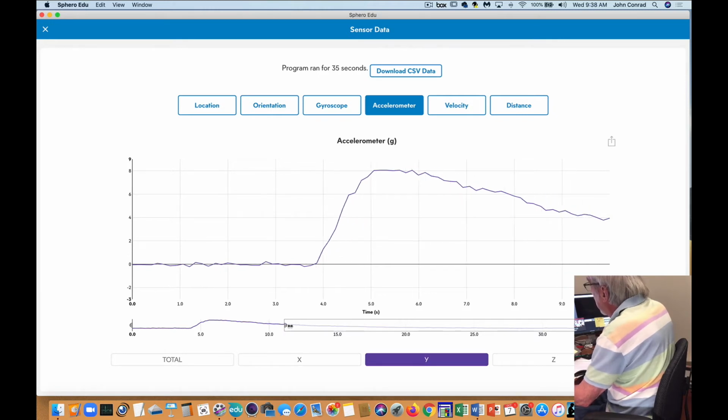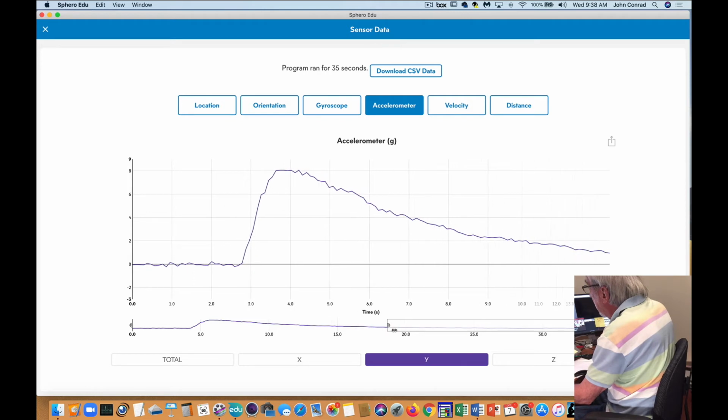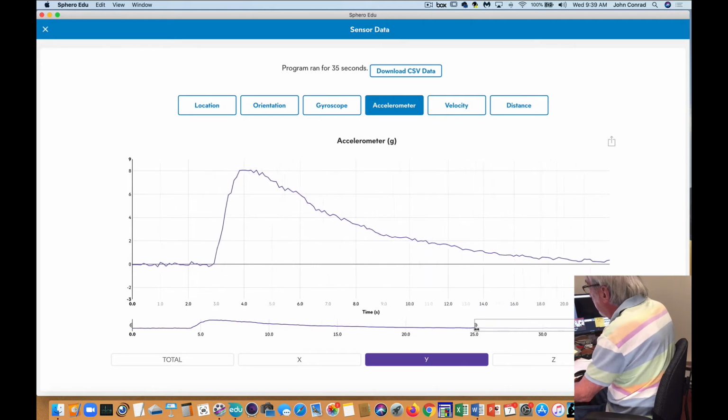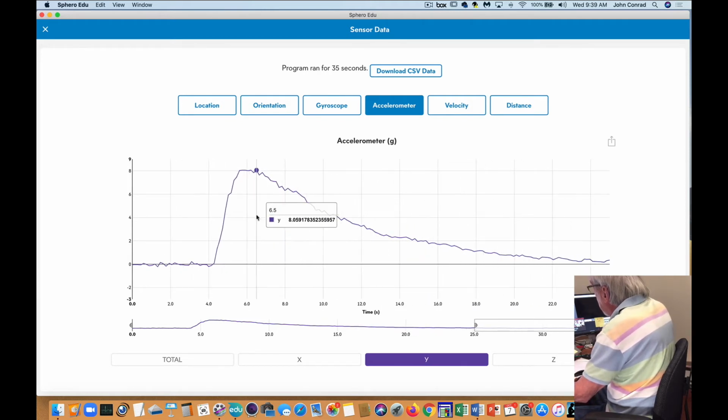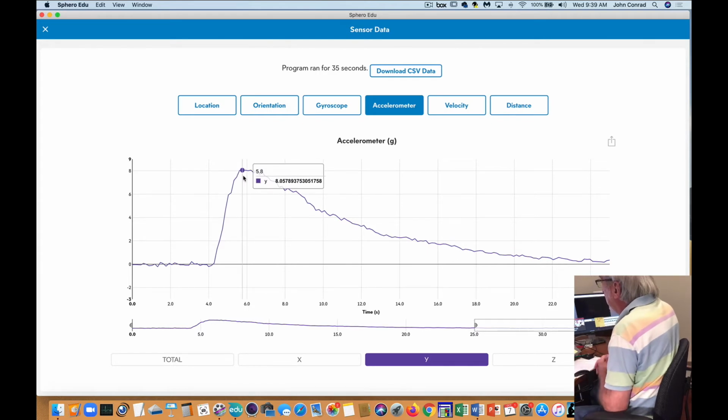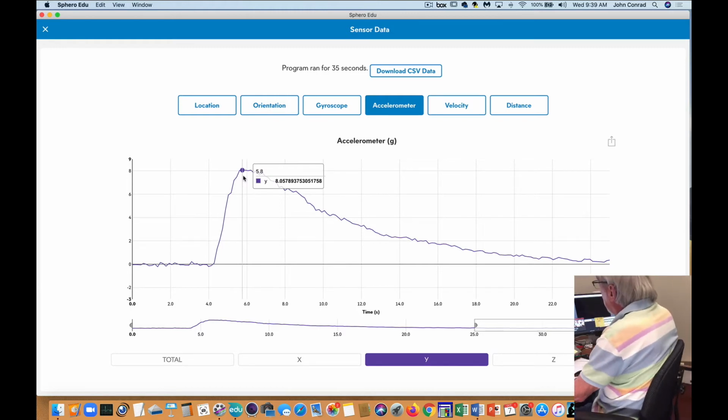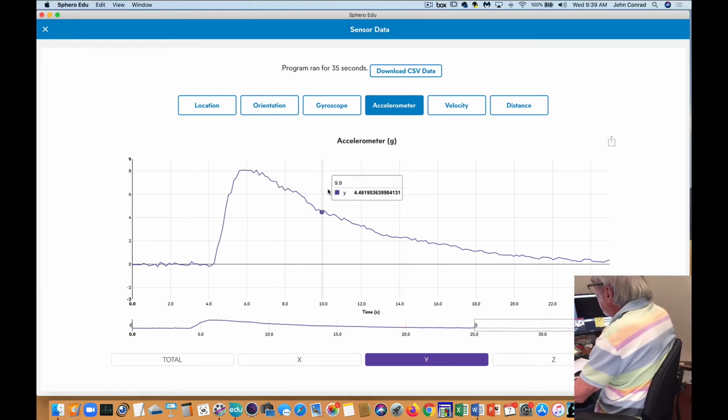And this now is the whole time history of the accelerometer data. And if you look very carefully, actually this barely started to flat top at 8 Gs. 8 Gs is the maximum acceleration that the accelerometer can read. So we should have slowed down, but this will be a good data set to look at, though.